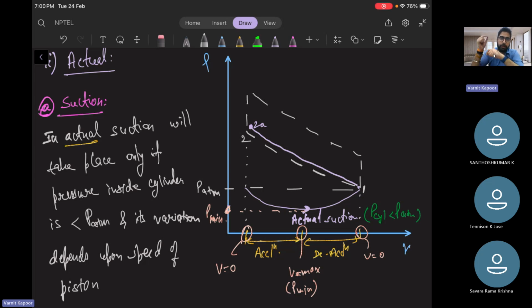There will be some microseconds gap when the piston will be reaching the top dead center and moving back to the bottom dead center during the expansion process. Okay? So there will always be a microsecond gap. So what happens? The spark doesn't begin directly when the piston has reached the top dead center. Spark begins just before the top dead center position.